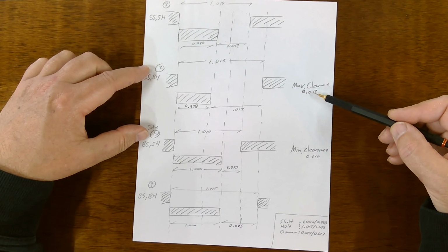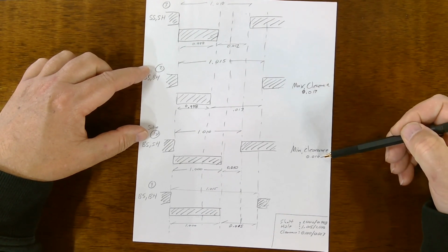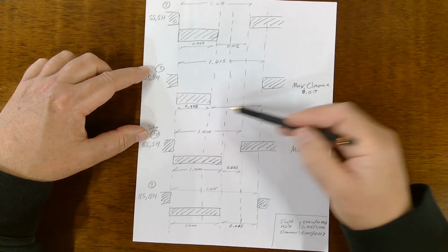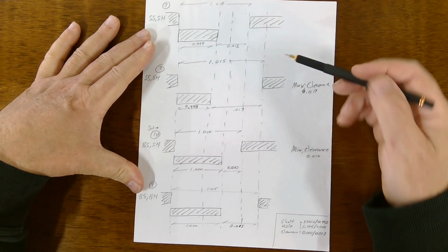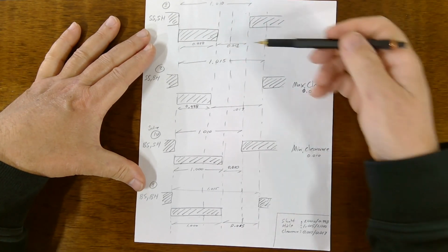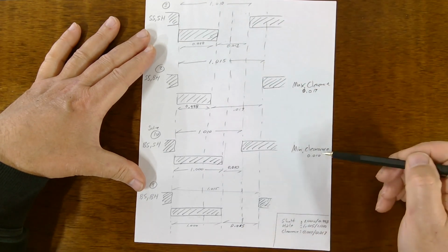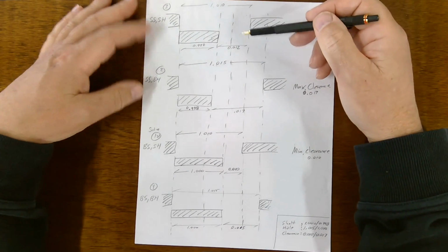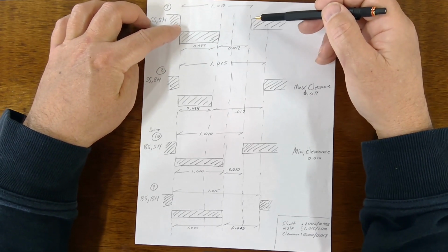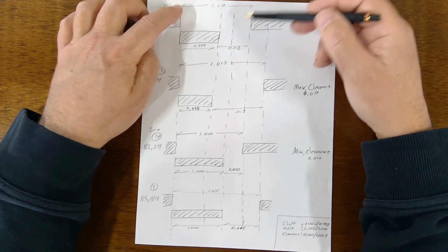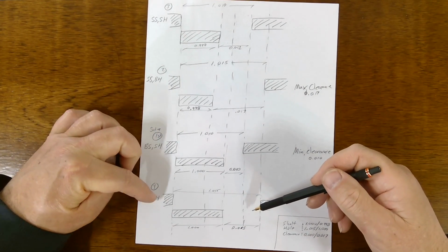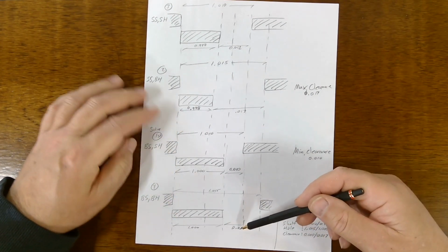So you solve these first, and you end up with a minimum clearance, this gap here of 10, and max of 17, this gap here. Then for the other 2 cases, the clearance will fall between 10 and 17. You see, the clearance is 12 here, and the clearance is 15 here, which is between 10 and 17. That's the other 2 cases where you have smallest shaft and smallest hole, 998 and 1010, and that works out to 12 thousandths, which is in the range here. And biggest shaft, biggest hole is 15, biggest shaft is 1, you end up with a 15 clearance.